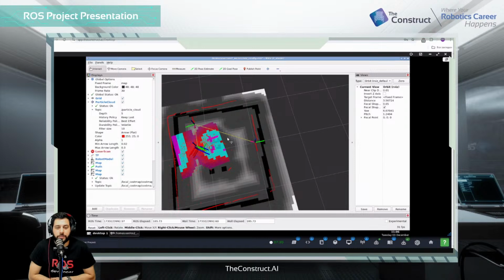This is a local costmap, so it utilizes not only knowledge about the map that was made before, it also uses data from the laser to see the obstacles that are not on the map. Right. So it can plan to be more aware of its current environment.